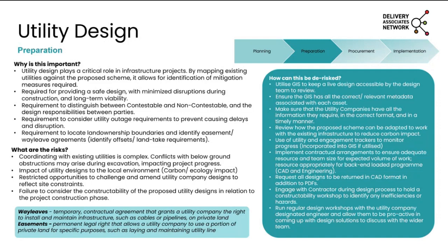Any utility designs that you put forward will impact on the local environment. It's both underground and overground. Also need to consider the temporary case during construction. What will the impact be during construction in terms of traffic, in terms of temporary facilities that are required during these works? What are the environmental impacts? How can these be mitigated against? All of this forms part of the design. It's not just a case of designing a new pipe from A to B.